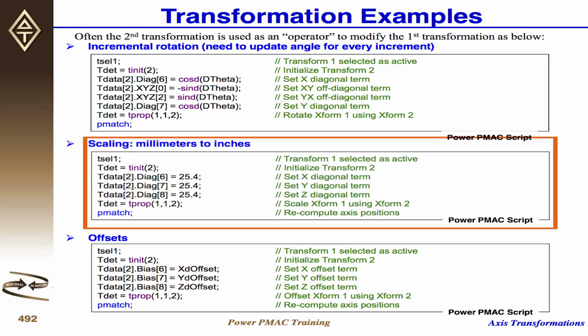So you don't mess up your original axis definition scaling. You just apply this. You can actually have two buttons: when you click one, you want to use inch, and you apply one of the scaling matrices, and it will do that for you. Whatever you input from your motion program, you don't have to scale in the motion program because we do that for you.